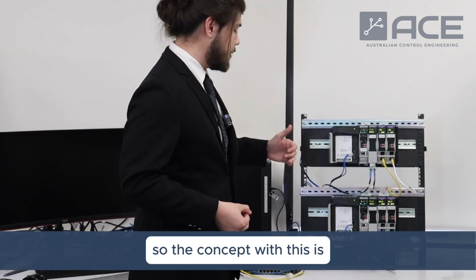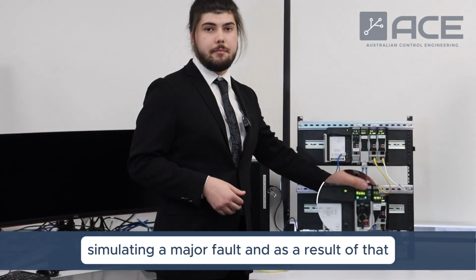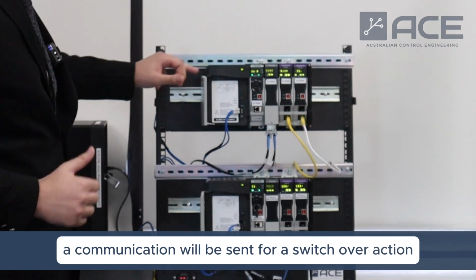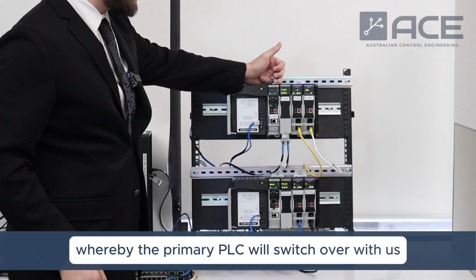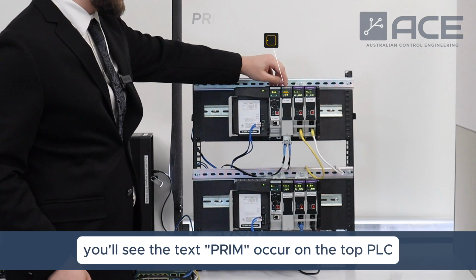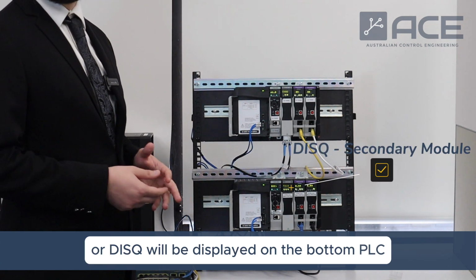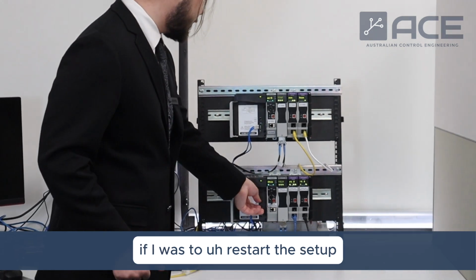So the concept with this is I will be flicking the power off on the primary PLC, simulating a major fault. And as a result of that, through the active channel of the redundancy module, a communication will be sent for a switchover action, whereby the primary PLC will switch over with our synchronized secondary. You'll see the text PRIM occur on the top PLC, whilst disqualified or DISQ will be displayed on the bottom PLC if I was to restart the setup.